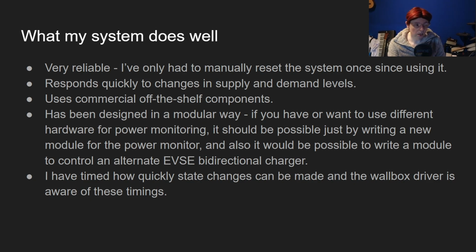Oh, just one thing I'd like to mention as well. If you are going to go with a Shelly EM, I recommend not bothering with their 50 amp CT clamps. I originally bought a 120 amp and a 50 amp one because I thought that's all I would need.